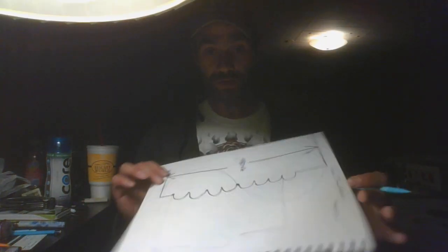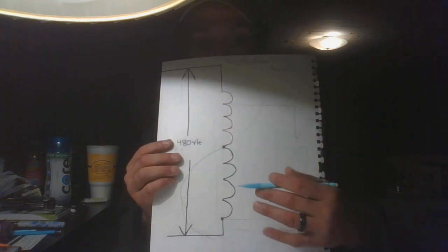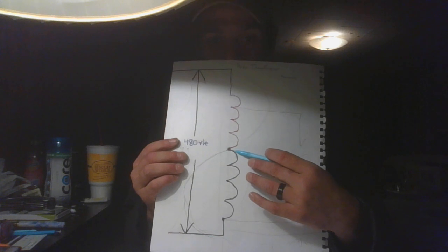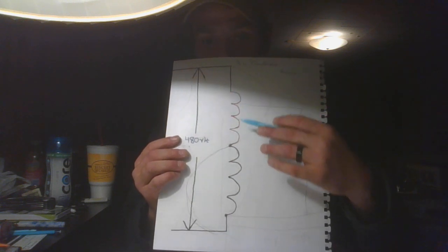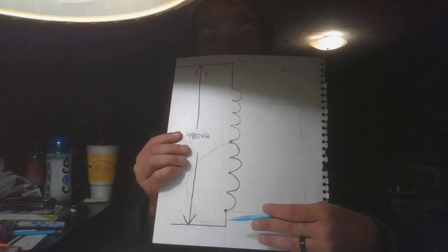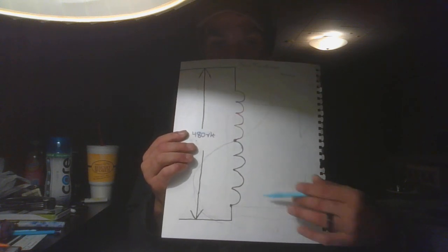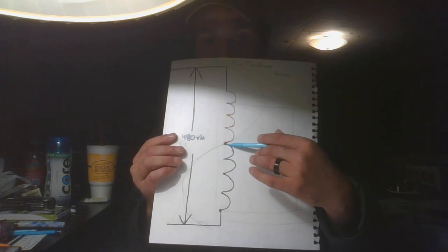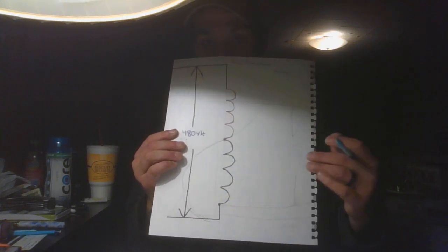Okay, now, the only thing that's going to differ is if we feed this with an alternating current circuit, our point of 0 potential is going to be right dead center of the winding. So we're going to have a maximum positive voltage from the top of the winding to the center of the winding. And from the bottom of the winding to the center of the winding, we're going to have a maximum negative voltage. But the point of 0 potential is right dead in the center. And from each end of the coil, we're going to have an end phase voltage. We've got a 180-degree displacement.